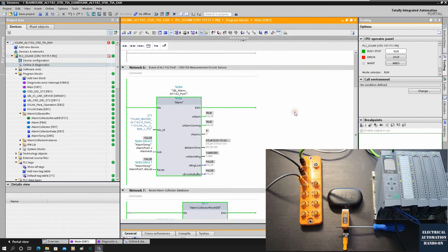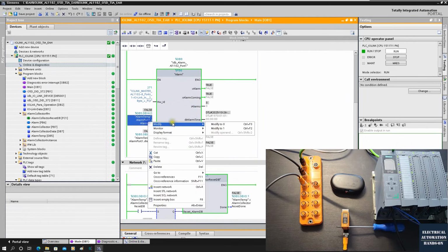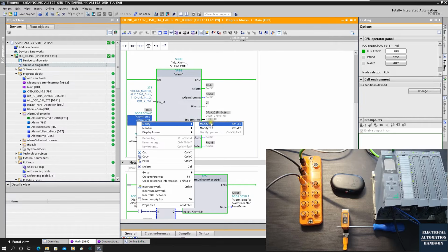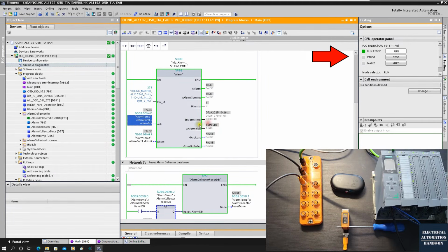Now we can remove this object and let the system return to normal. Now we can see the alarm from the CPU has recovered. But this buffer, we haven't acknowledged yet. That's why it still shows alarms 3 happened, because when I was moving it, it triggered a couple of times. So it shows this alarm is still there, and we can acknowledge it. Acknowledge the buffered 3. Okay, we can acknowledge.